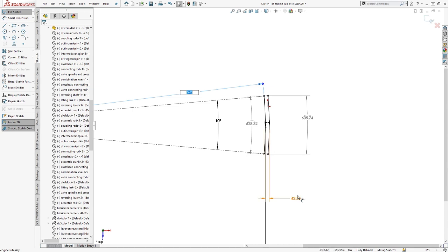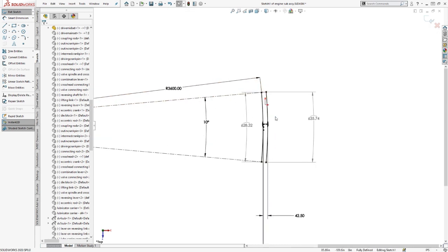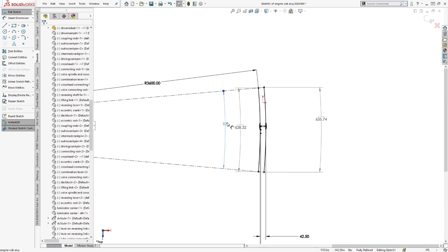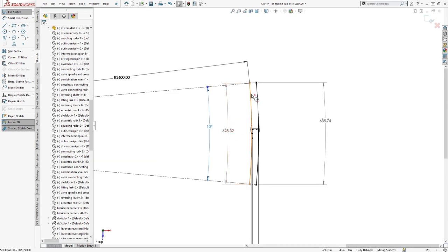So this radius is that much bigger than this radius. And the arc length is 10 degrees. So we're coming in at -5 and we're leaving at +5. And we've done it over a radius of 300 feet. Well, for that configuration, this inner arc has an arc length that needs to travel of 628 inches. The outer is longer at 635 inches.